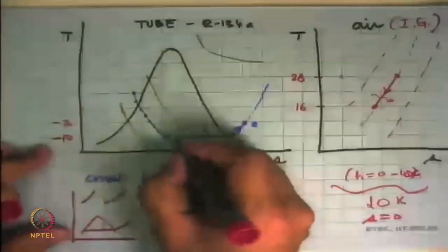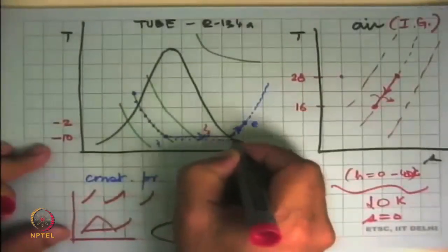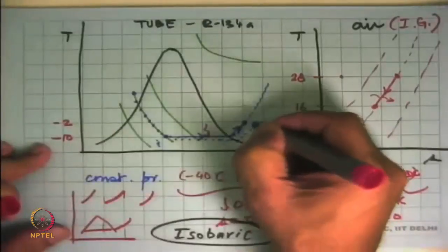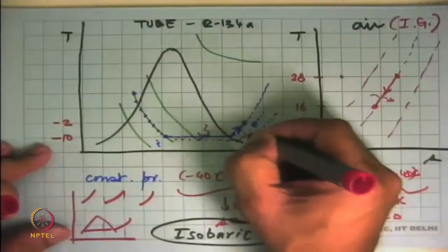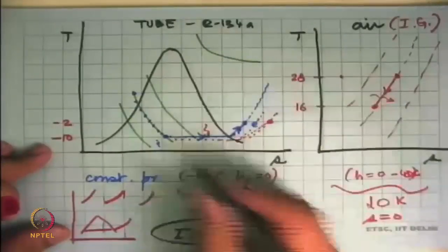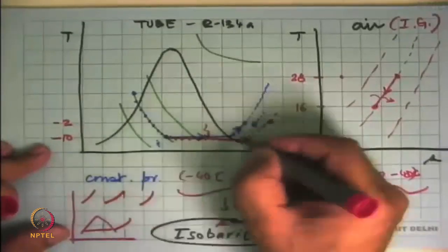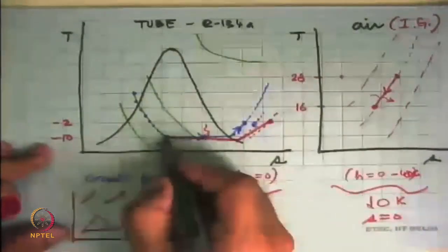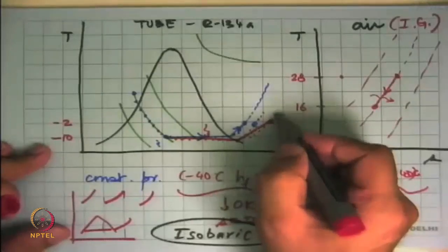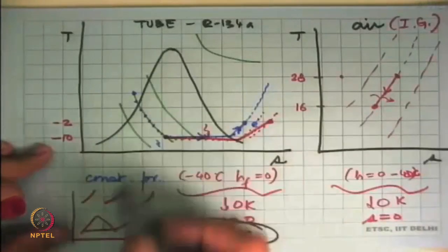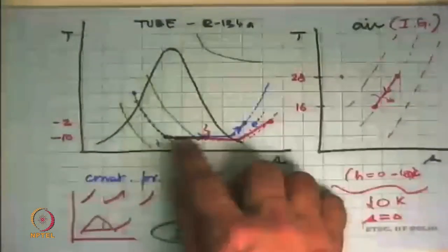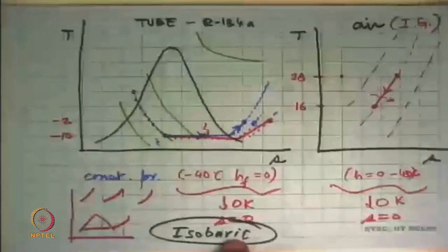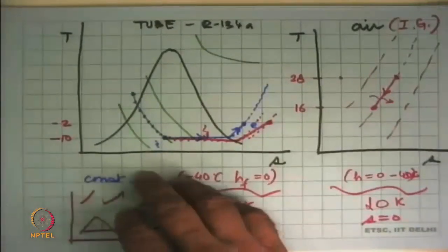It will be that as it keeps going, there's a slight pressure drop all the time. It comes over there, then it would have gone along this, but there's a pressure drop, so the lower pressure isobar is there, so from here it will go and finally end up at this place. So the real substance will go like that. And the pressure here is less than this pressure. But in the analysis that we do, if that is not given, we assume it to be a constant pressure heat transfer process. Okay, so that is the idea of a heat exchanger.